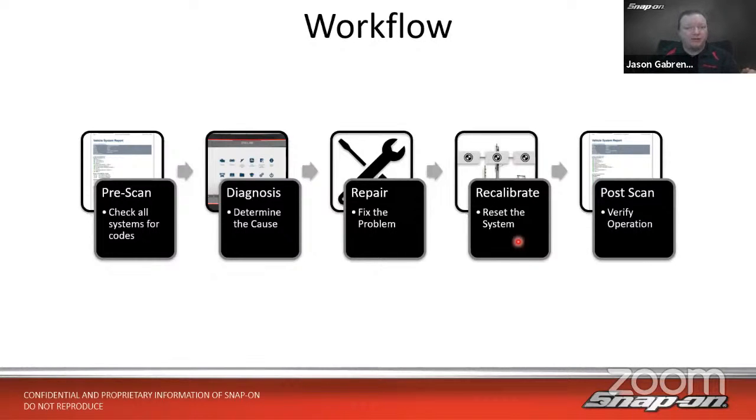So you want to definitely go in there and check and see, are there any of these resets, relearns, calibrations that apply to this problem? Then once we're done there, we can clear the codes and then take it on a nice drive cycle road test to make sure that none of those issues that we were trying to solve come back.